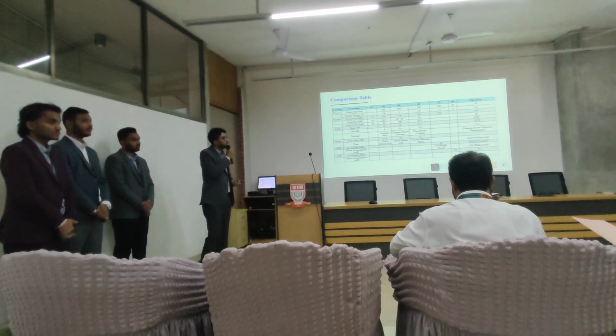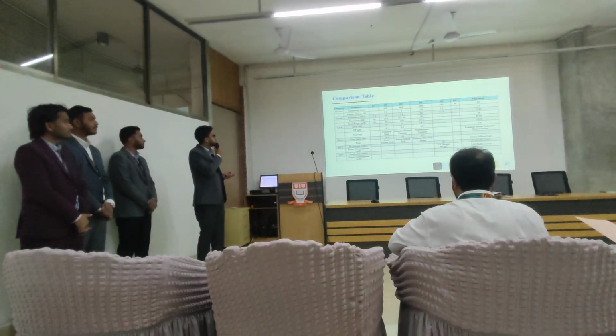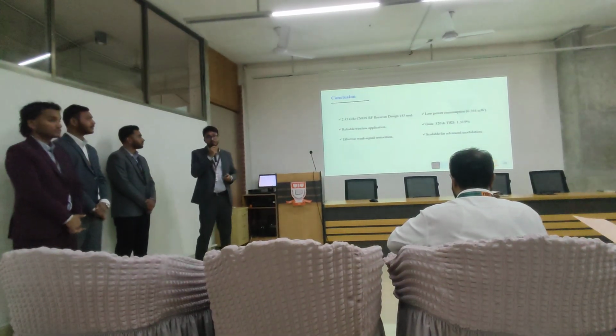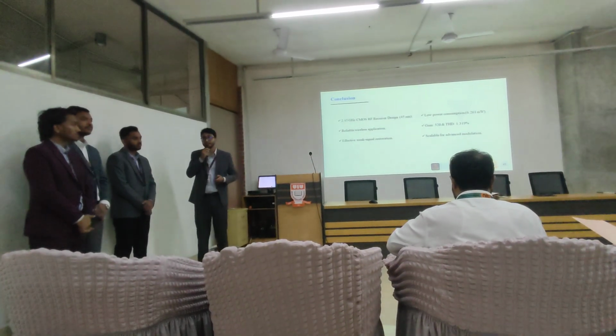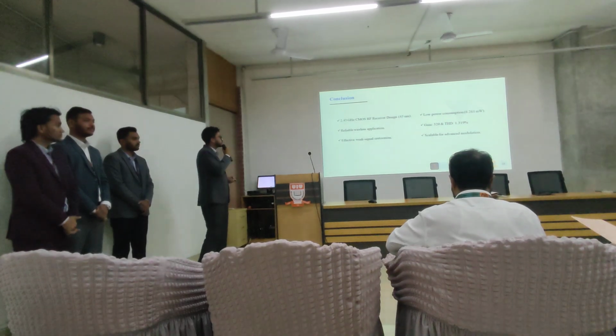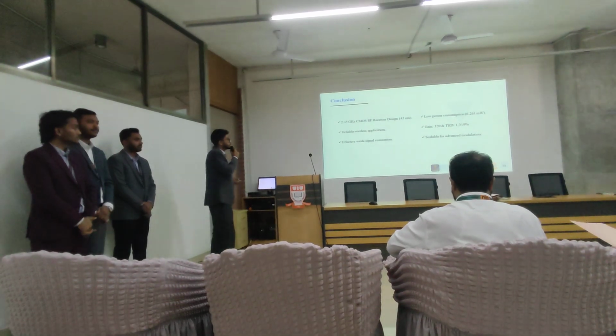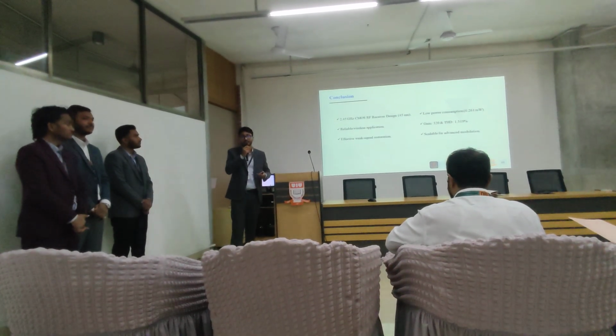Here is the comparison table of our RF receiver block. In conclusion, we have successfully designed our 2.45 GHz RF receiver with power consumption of less than 10 milliwatts and total harmonic distortion close to 1%.